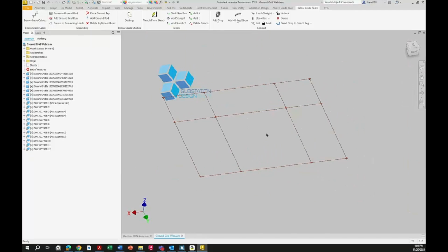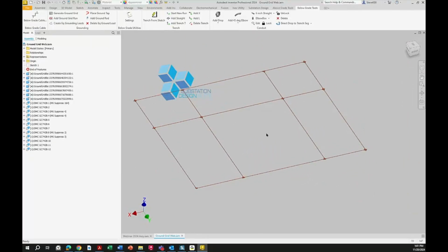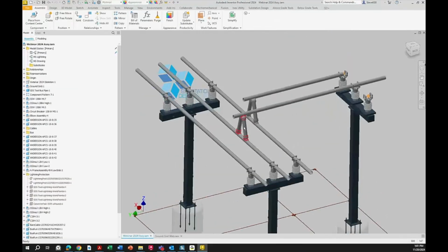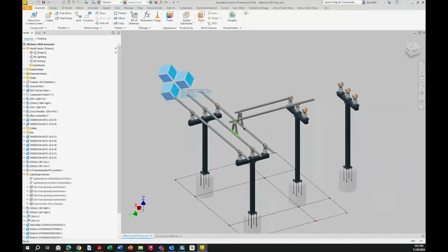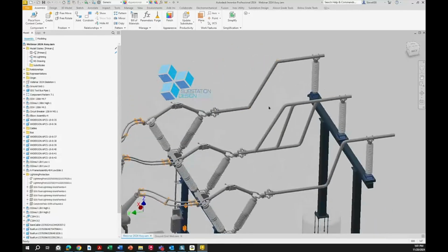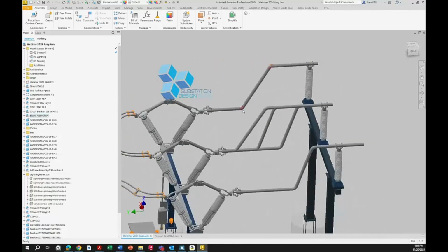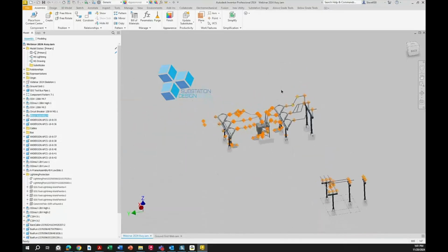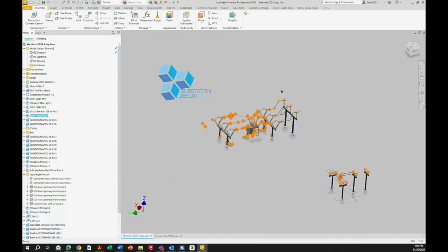I've had a lot of people asking me about doing this type of thing, so I think this is a good one as well. I like the slider tool. I like the bus tool of changing the A-frame to the direction I want. The other tools here with the bend, I prefer to put elbows in. I think at site they would prefer elbows, and I tend to always put in elbows. But if you are bending pipe, we're able to bend it and get a shape that we might want. So it's 1:01, we're a minute past. I covered everything.